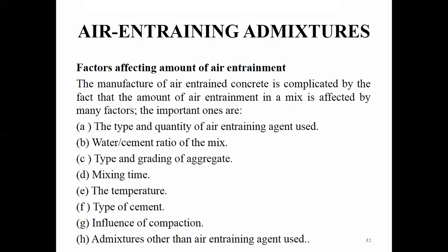The other admixtures: you will be using some other admixtures in addition to the air entraining admixtures, right? This will also surely affect the amount of air entrainment. If you are using fly ash, you know fly ash is one of the mineral admixtures. Since it is pozzolanic in nature, you will be adding it to improve the shrinkage properties in the concrete, right?